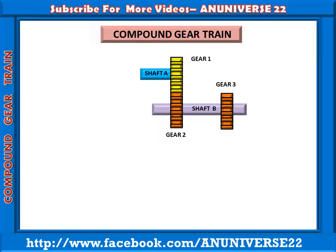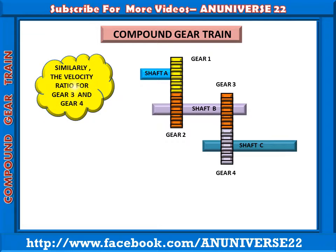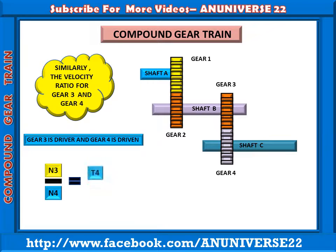Another gear is also mounted on shaft B, that is gear 3, and this is another shaft C on which gear 4 is mounted and that is matching with gear 3. Similarly, the velocity ratio for gear 3 and gear 4, here gear 3 is acting as a driver and gear 4 is driven. Then the velocity ratio for both the gears, that is N3 upon N4 equal to T4 upon T3. N3 is the speed of gear 3, N4 the speed of gear 4, T4 is the number of teeth on gear 4 and T3 is the number of teeth on gear 3. That is equation number 2.